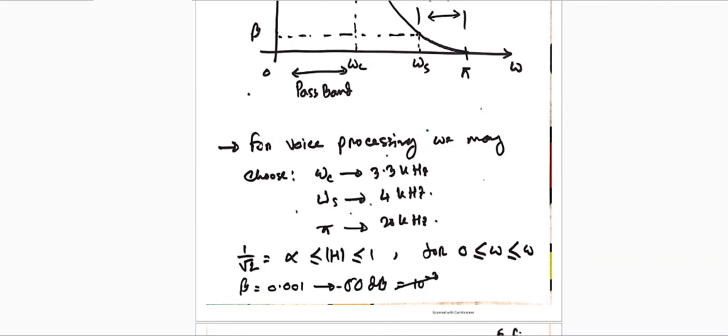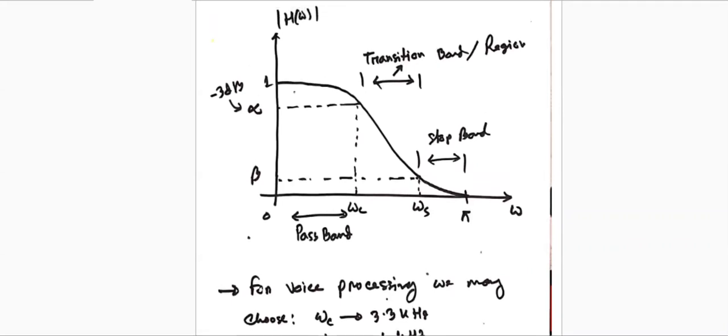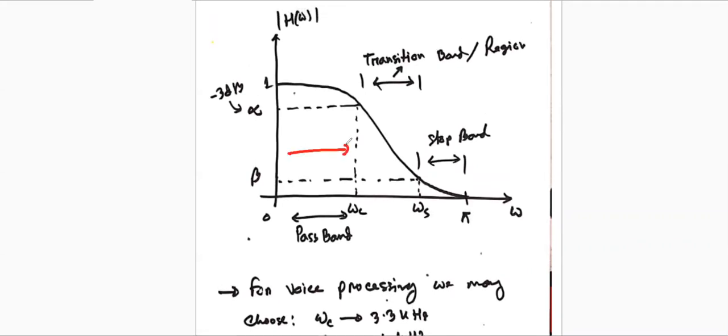That means at the cutoff frequency, the 3 dB point. In between, the amplitude can be very flat, like 1, for the ideal case. But for the practical case, it will be decayed, and in other cases it might change like this.